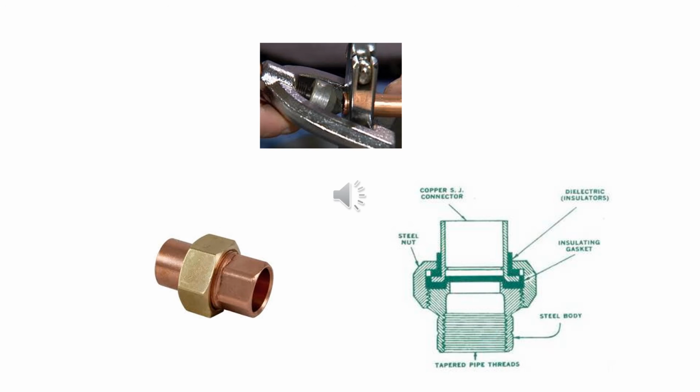On most domestic water heaters, steel return and supply lines protruding from the tank are what is connected to your copper water pipes, and that actually creates a problem. When you put two different metals together in the presence of an electrolyte, in this case tap water, you get a reaction called galvanic corrosion.